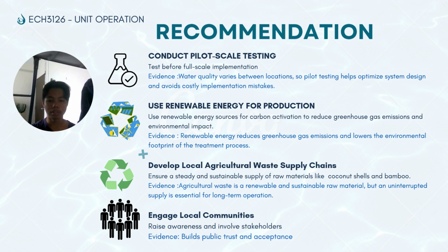Okay, based on our analysis, we recommend using activated carbon adsorption for drinking water treatment. However, successful implementation depends on several important conditions. First, pilot scale testing should be carried out before full scale installation because water quality may differ from one location to another. Testing helps determine the best operating conditions and reduce the risk of expensive implementation mistakes.